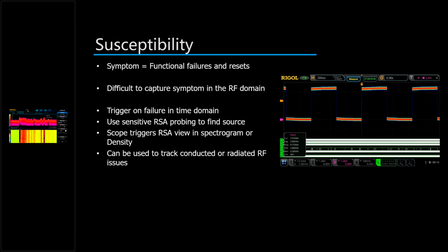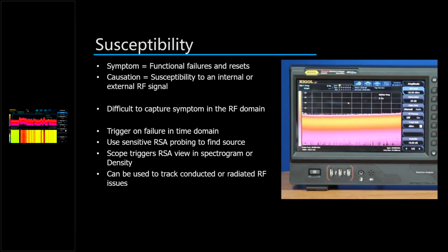And here's how we really track it down, using the spectrum analyzer. We can track it down to an RF problem. And so in this case, what we see is an occasional wideband pulse that's really from a relay. So this is the RF envelope of a mechanical relay that we've tested, and a problem like this can really get into your embedded system.